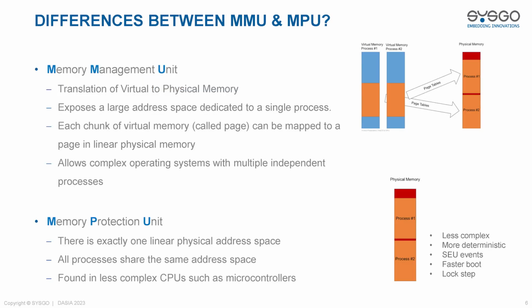When we are talking about memory, we refer to all the locations that can be addressed by a CPU. It might be ROM, might be RAM, might be I/O memory as well. The MMU or the MPU is the way the processor controls the access of the operating system and the applications to these types of memory. There is usually one MMU or MPU per core.